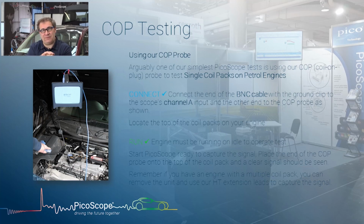This is really important, and Phil will show you in a minute. Really important that you get it nice and central on the top of the coil pack so you get a nice clear signal, and also if you're comparing one coil pack against another, you keep it in the same place on all of them.